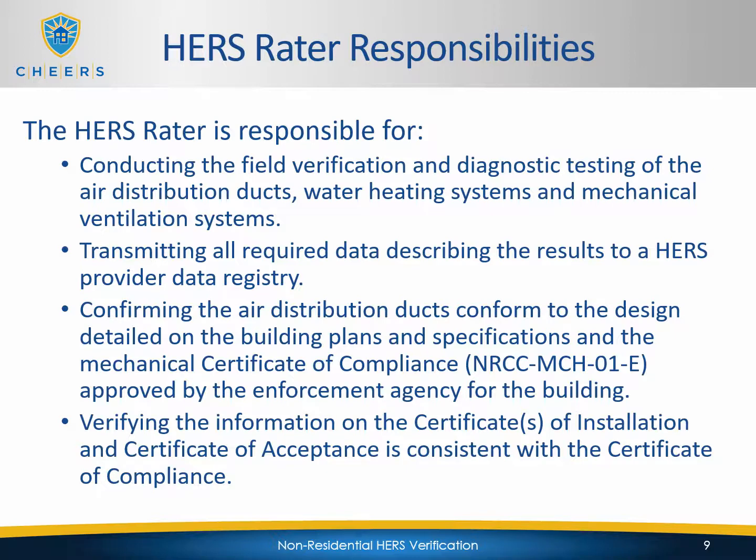The HERS rater will be responsible for conducting the field verification and diagnostic testing of the air distribution ducts, the water heating systems, and mechanical ventilation systems. You'll also be required to transmit all required data describing the results to a HERS provider data registry. Also confirming the air distribution ducts conform to the design detailed on the building plans and specifications, and the mechanical certificate of compliance, which is the NRCC MEC 01. And this will be approved by the enforcement agency for the building.